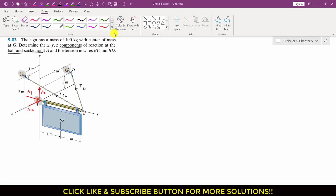Now first I will write TBD, TBC and the weight of this sign board. Let me represent the weight of this sign board as well. The weight will be acting vertically downward, and this has a mass of 100 kg, so 100 times 9.81, which is 981 newtons. So I will write that this weight is 981 newtons and it is acting vertically downward.